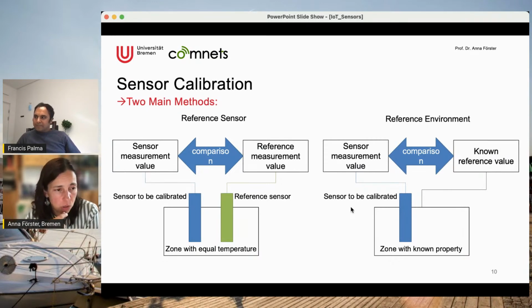If you're talking about the input voltage of the ESP, typically there are no spikes up, because no battery can really deliver more voltage than its nominal one. Typically it's less. If it goes way below what a component can manage, that component will switch off.